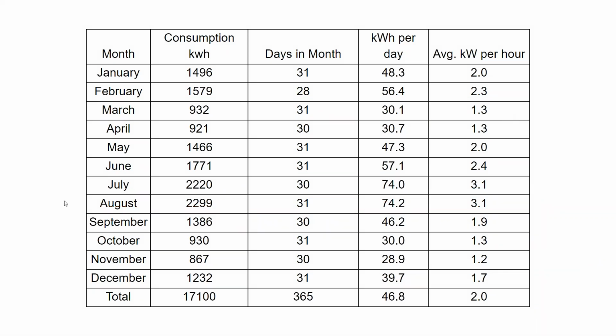Let me look up the questions. Okay, thanks for letting me know about the audio. So basically what we did is we charted the battery level after making a guess, and then by visually exploring the chart, we could identify that actually we could reduce the battery bank size by 30 kilowatt hours if we accept a little bit of generator runtime.